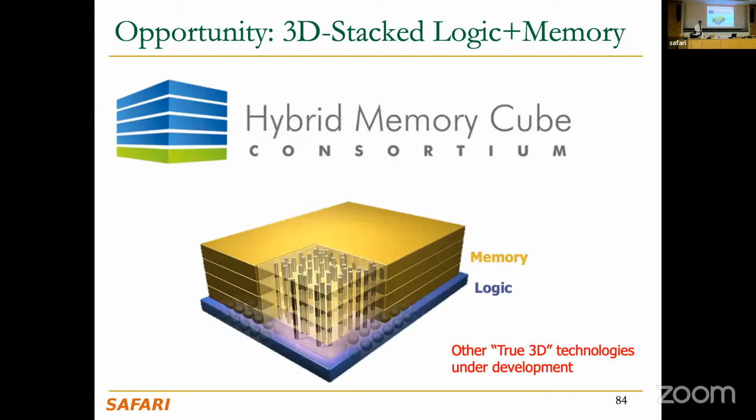And together with that, as I mentioned before, there was a push from new technology around 2013, these 3D-stacked memory architectures, that allowed you to implement these processing near memory solutions with low cost. In these 3D-stacked memory architectures, you stack the memory devices together using vertical connections, and to put everything together we use a base die, which in HMC nomenclature is called the logic layer, manufactured using the same CMOS technology as your processor. So you have two manufacturing technologies: DRAM is one process and logic is another, and if you try to put them together, they create problems for each other.